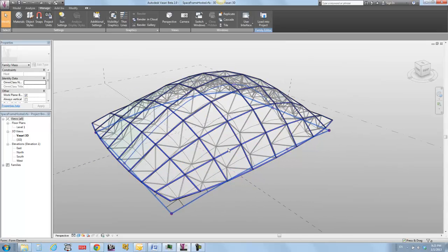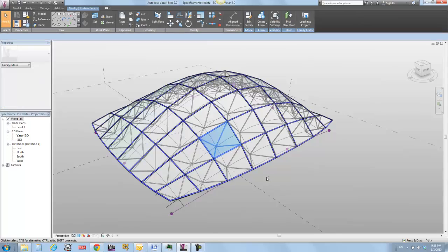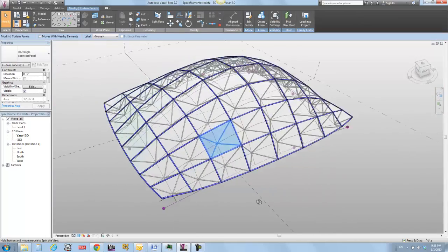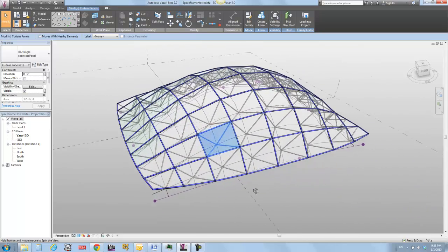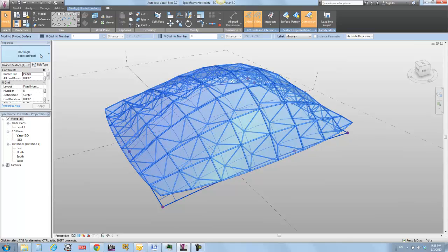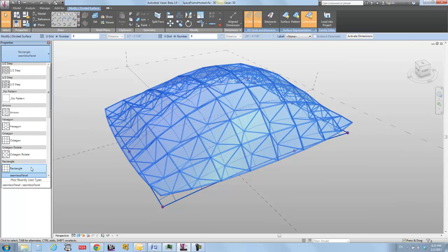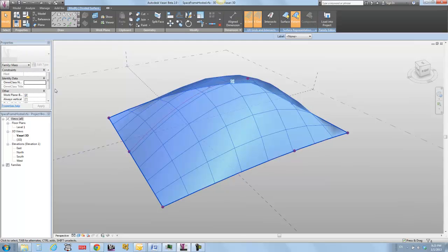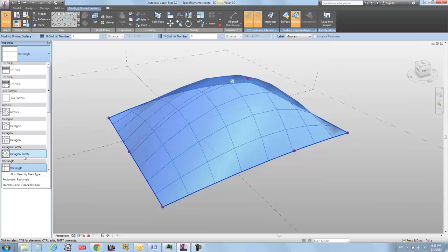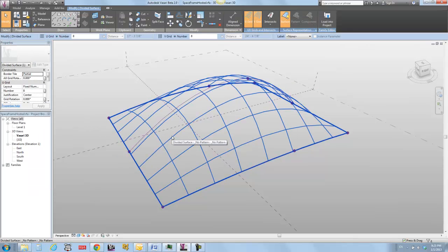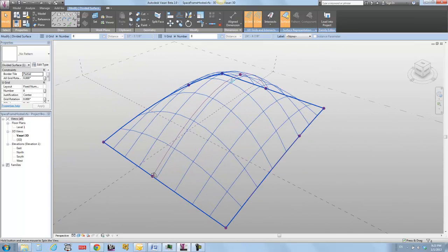So what I've got here is a divided surface that has one particular funny curtain panel put in on it, and I'm just going to dissect this a little bit to show you what it's put on. So I've got this curtain panel. This curtain panel is in turn hosted into a surface that has been divided and patterned like this, and I'm just going to reduce this back down to its basicness. So I've got a surface that I've just hit divided surface, and I've gotten this thing on it.